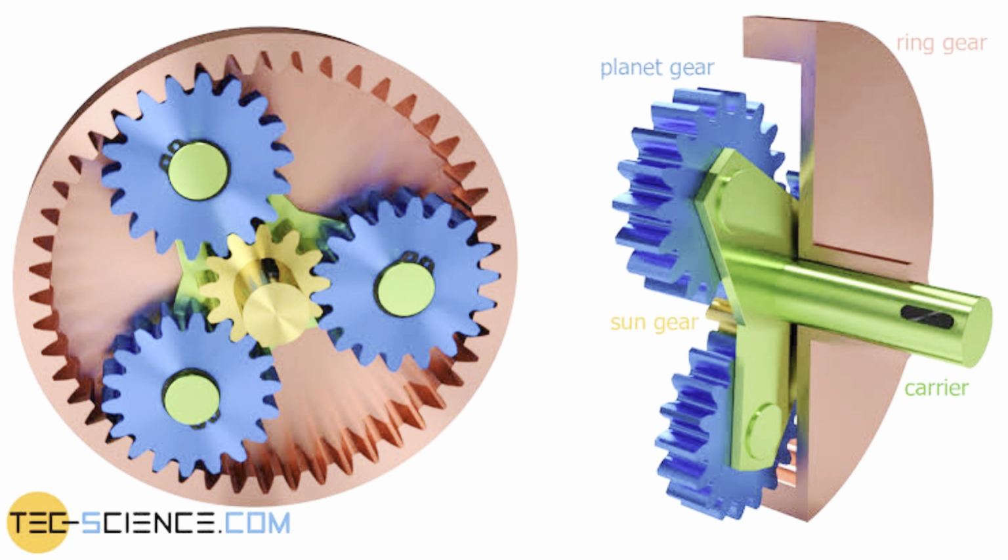One example of a way that this system can be used is by connecting the ring gear to the input shaft coming from the engine, connecting the planet carrier to the output shaft, and locking the sun gear so that it can't move. In this scenario, when we turn the ring gear, the planets will walk along the sun gear, which is held stationary, causing the planet carrier to turn the output shaft in the same direction as the input shaft, but at a slower speed, causing gear reduction, similar to a car in first gear.